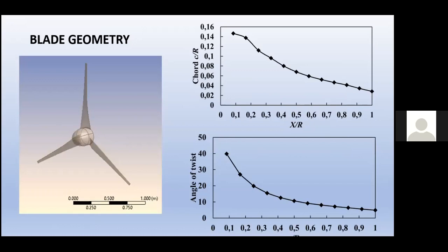For this analysis, the turbulence model k-omega SST is being used, from which a rotation speed close to 230 revolutions per minute has been obtained, which is low compared to the expected one, since the calculation was made thinking of a speed close to 260 revolutions per minute. For this reason, the work is still under study in fluid dynamics.